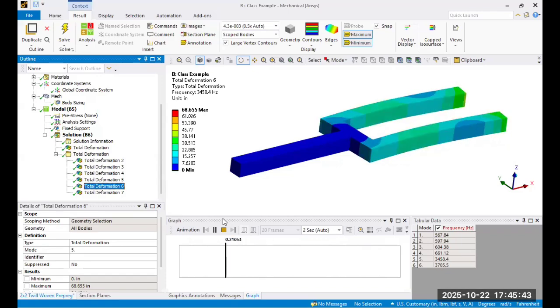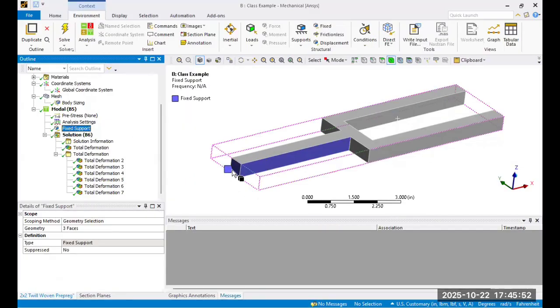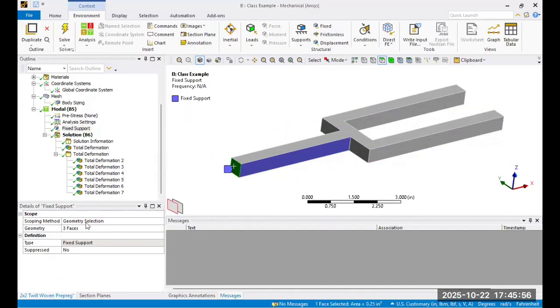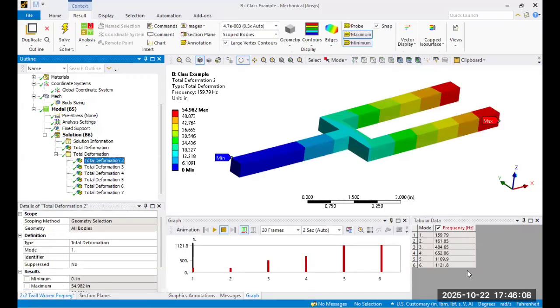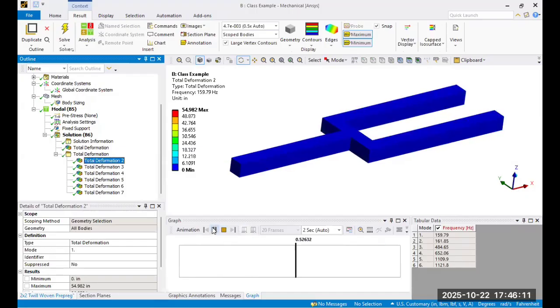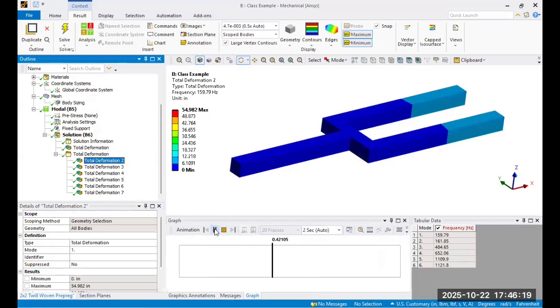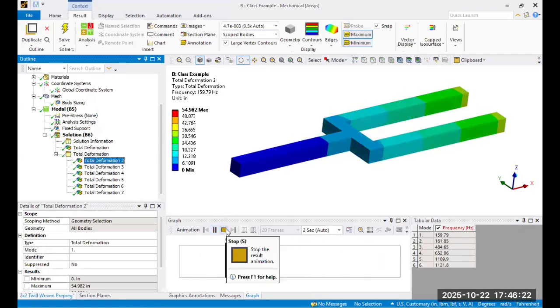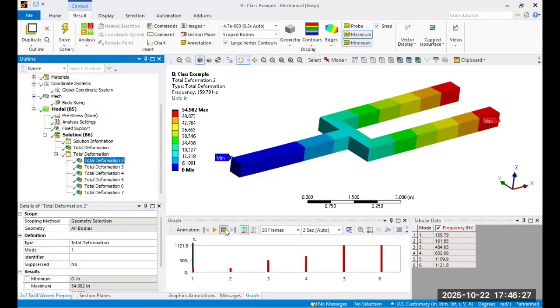So what happens? Because now you have more frequencies that are potentially available for the system to get excited, a lot of times these tubings will blow apart the minute you run the engine, because now you have more modes to be worried about. So in design, you try to keep the fundamental frequencies of the tubing higher by providing support. You bring the supports closer, so the fundamental frequencies of the tube are higher. And by them being higher, you're pushing the frequencies so far away from the forcing functions that you should not have a problem. So this is an important aspect of design that we're trying to teach you here.